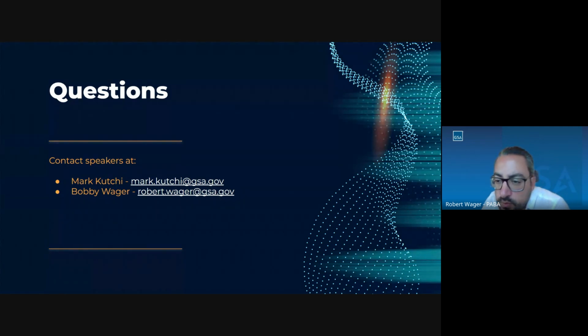Greg said, say they make ducted condensers. Thanks, Greg. Ductless split systems are great for this. Okay, let's be very clear, though. When we talk about ductless split, you're still not locating a ductless condenser above a ceiling plenum. So let's just be very clear there.